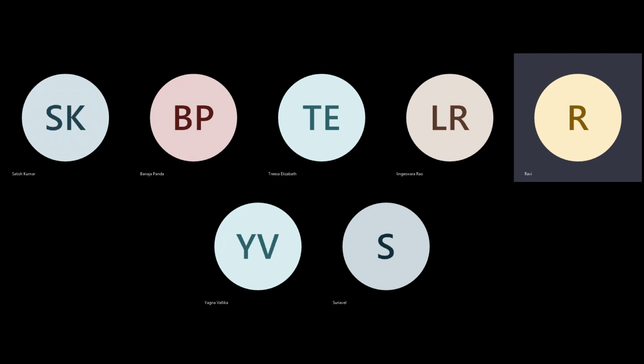This is called muxing. Yeah, memory muxing, you have 3-4 options. They will give thin and narrow, 4x1, 2x2, like that. You can look at which muxing. You should ask what muxing options are available for which memory, because mostly the front end would have chosen. But whether that fits my criteria, you'll have to give that feedback. This is not meeting timing in physical design. I cannot floor plan. Once you give that feedback, they will go and change that, and again they will give one more.